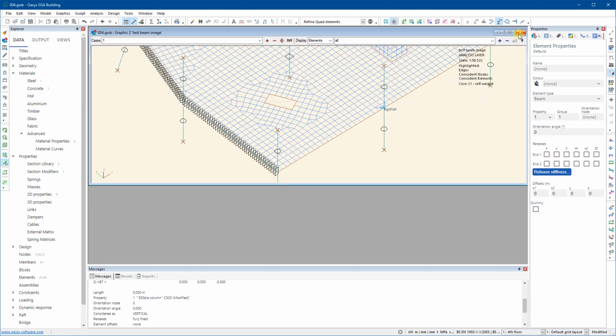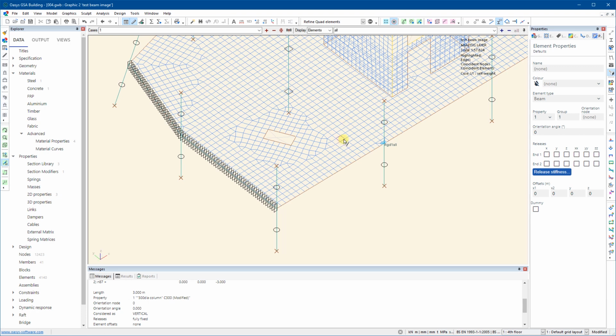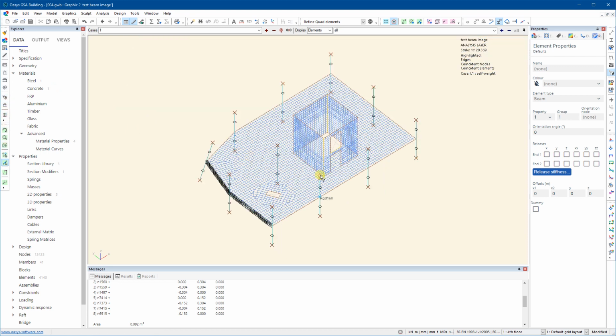So really the best way to look at all of this is to create models of your own, to apply simple load cases, to test the actual models, maybe run it under a simple self-weight case to see what happens. Maybe test the orthotropic properties by changing from the same E value in each direction and then slowly reducing the E value in one direction. You should see the results starting to change, going from a multi-way spanning slab, say, to one that's only spanning in the stiff direction. That would be a way of checking that it's behaving as you expect.